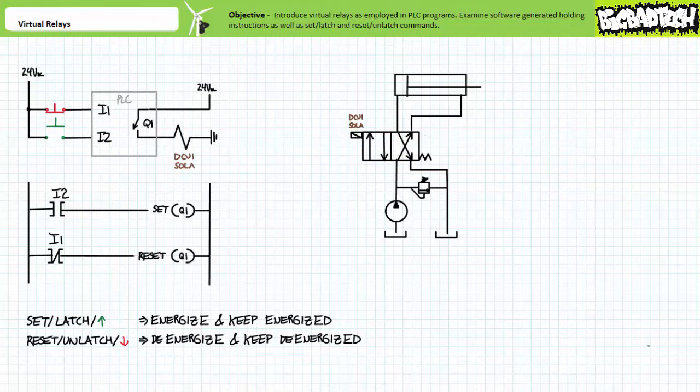Before we continue, I'd like to draw your attention to the break instruction examining I1, the normally closed red push button in rung 2, in series with the reset or unlatch command for output Q1. My question is this: why? Why is it a break instruction rather than a make instruction? If you've been following this lecture series in its intended order, you'll note that the break instruction in this scenario is necessary since the electromechanical nature of the field input device attached to I1 is normally closed.